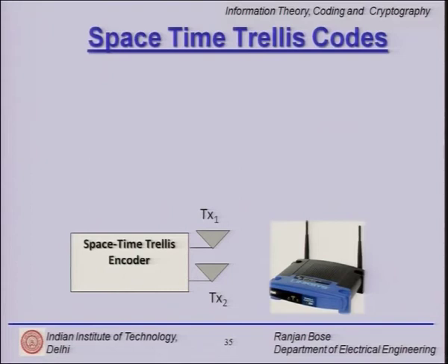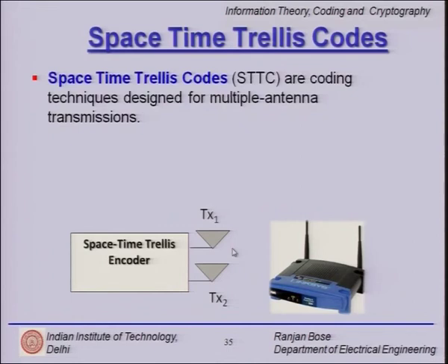So, we have now two transmitters. So, symbol 1 is sent from transmitter 1 and symbol 2 is sent from transmitter 2. It is a very logical extension, and I can extend it to NT antennas, NT standing for the number of transmit antennas. So, what happens if we do this? This kind of a scheme is called space time trellis codes, because we not only use the space coordinate, but also time coordinates. So, in different time instances we have different pairs being sent from transmitter 1 and transmitter 2. So, we are curious to find out what happens.